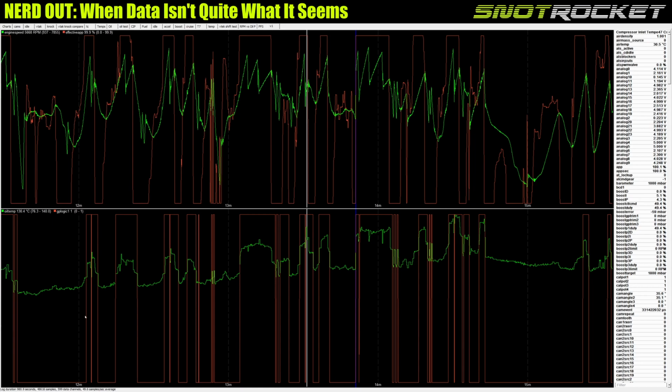And that's, you have the thing called a ground plane in a car, which is basically 0 volts. Cars run on 12 volts, roughly, but 0 volts, which is ground, earth on a car, because the entire chassis is earth. But you can get slight variations in the ground plane because cars are an inherently electrically noisy place. You've got sparks going, you've got motors going, you've got actuators going. All of that stuff creates noise on the car. Cars are inherently noisy, but there are ways to protect against that. And so looking at this chart, it looks like there's some noise on the oil sensor signal, which is being influenced by the VTEC switching on and off.